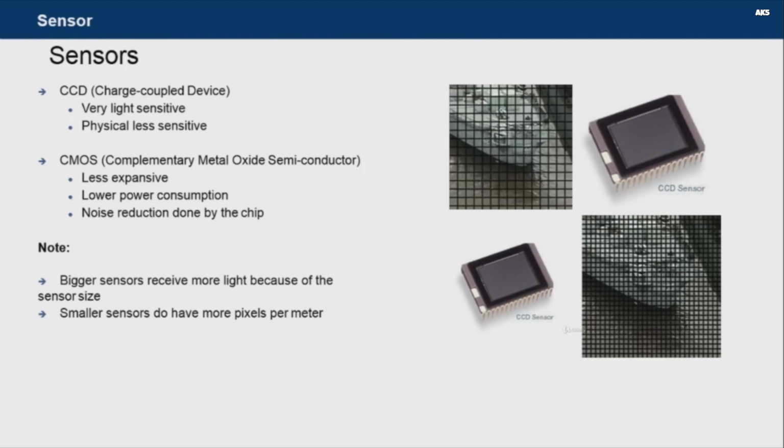So what's the difference between the both? CCD sensors have been used in cameras for more than 30 years and present many advantageous qualities. Generally, they still offer slightly better light sensitivity and produce less noise than CMOS sensors. Higher light sensitivity translates to better images in low light conditions. However, they are more expensive and more complex to incorporate into a camera. A CCD can also consume as much as 100 times more power than an equivalent CMOS sensor.